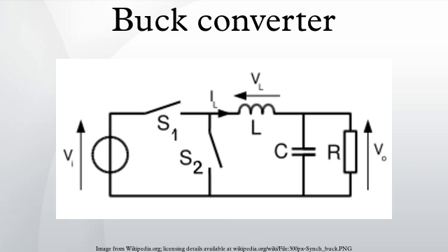Impedance matching: a buck converter can be used to maximize the power transfer through the use of impedance matching. An application of this is in a maximum power point tracker commonly used in photovoltaic systems. By the equation for electric power, where Vo is the output voltage, Io is the output current, η is the power efficiency, Vi is the input voltage, Ii is the input current, by Ohm's law.